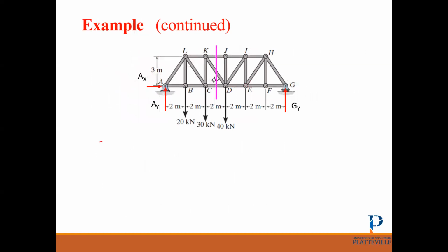All right, let's see the free body diagram. We have 3 reactions, 2 in the hinge and 1 in a roller. Then we decide which part is a good cut, how we can find the reactions. If we write sum of Fx equals 0, we can find Ax because there is no external load in the x direction, so Ax is 0, right?